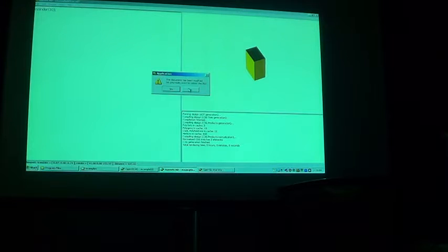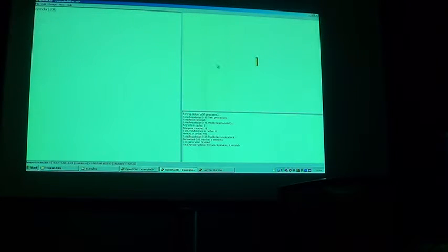Don't you need 2 dimensions for a cylinder? Interestingly enough, no. You will have to give them though if you want to specify something. So it interprets the first as, so if I just give it 10, it uses a default radius of 1, and it's just using that as the height. So you can specify them, and we can say things like radius equal to 5. So now we have a cylinder.